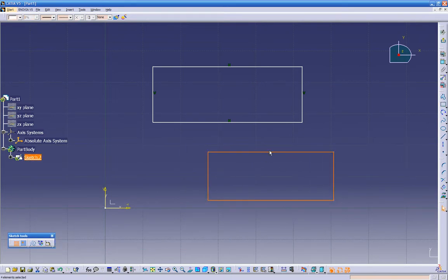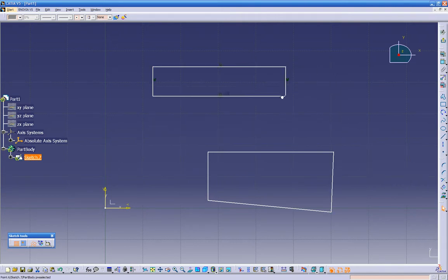We don't have the horizontal and vertical anymore, so if we're going to click on this point, we can distort it right away. It doesn't stay because it doesn't know it's a horizontal line. This right here, it knows it's a horizontal, so if I grab this point, I try to move it, it's not gonna do anything to it. But if we delete the V, watch what happens. See, we still can move it. So it's not a vertical line anymore.